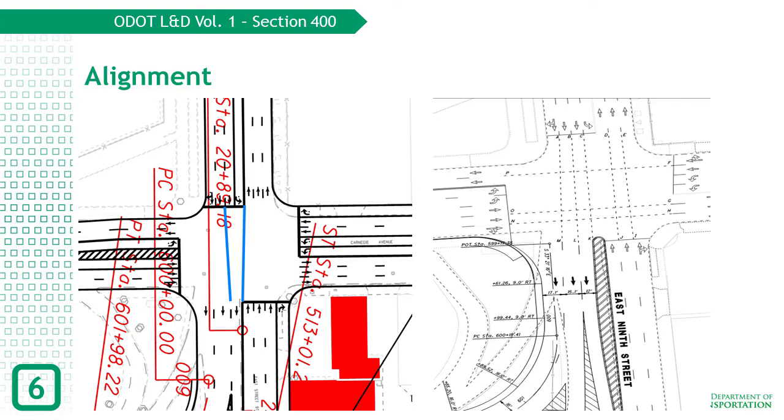The image on the right is that same intersection with some striping changes applied to improve the horizontal deflections. Note the striped out pavement on the south side of the intersection opposite the left turn lane to better align the through movements. This reduces the path overlap conflicts that were originally present.